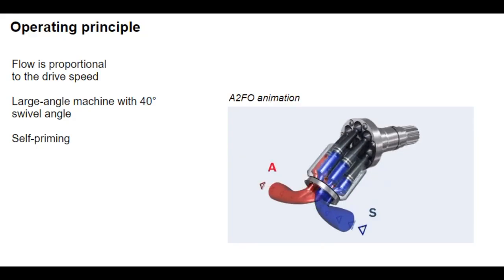Hydraulic fluid enters the increasing piston chamber on the suction side. At the same time, hydraulic fluid is pumped out of the cylinder chamber and into the hydraulic system on the high-pressure side. The hydraulic pump works in an open circuit, taking hydraulic fluid from the reservoir and feeding it through a directional valve to the consumer, such as a cylinder or hydraulic motor. The hydraulic fluid returns to the reservoir from the consumer through the directional valve.